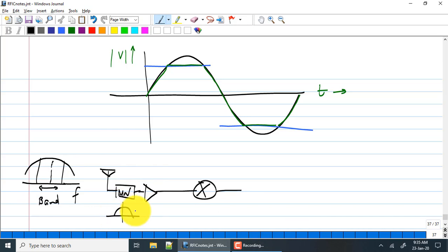This may have a strong frequency dependent function, because all the matching networks that you have seen, they are low pass, high pass, they have a certain Q, etc. What about the LNA? It turns out that the majority of LNAs are also high Q. What does this mean? If I actually take a receiver, or in fact forget the mixer, because the mixer is a more complicated block, if I just apply a single sinusoid